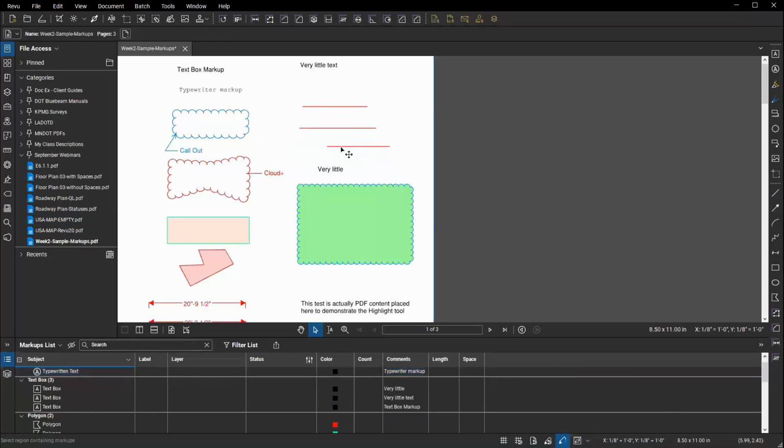And there's a couple of different ways of changing your default. The first is you go to draw a markup, whatever it is, you change the properties of the markup to whatever you want them to be, and then before you start placing items into your drawing, you go to the left-hand side of the properties toolbar where it shows you the markup type you're working with. And just like last week, I mentioned these little chevrons. There's a chevron there indicating that there are choices underneath here that you can use if you choose to do so.